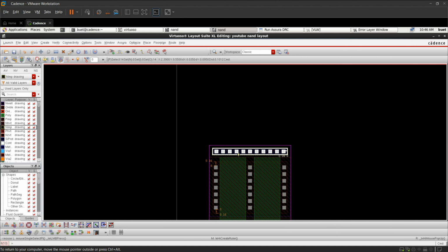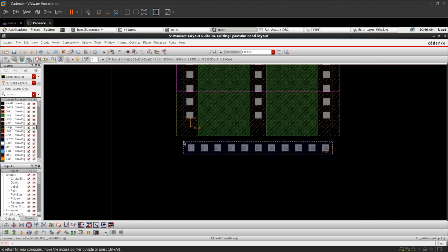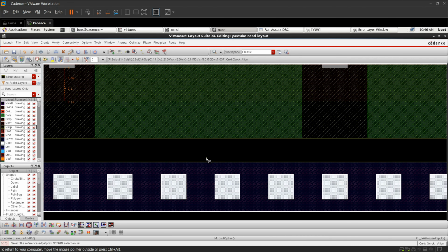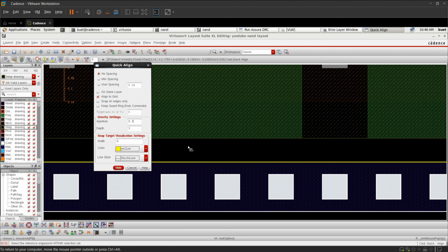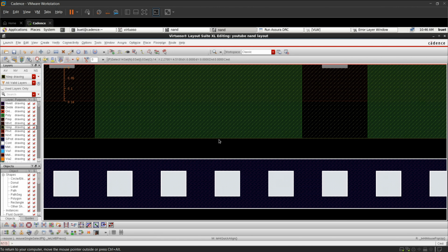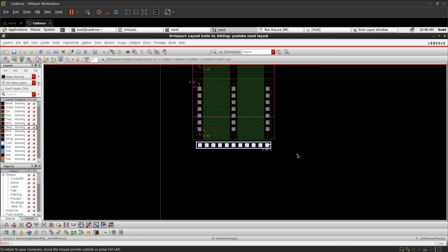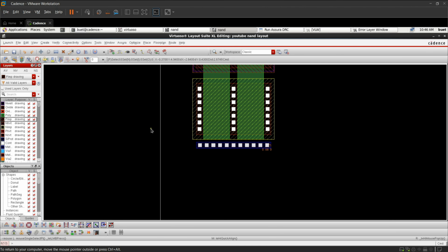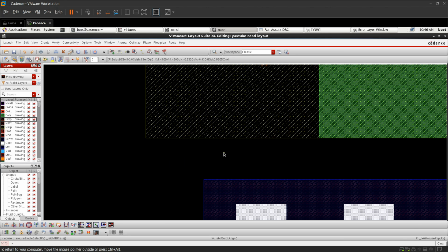As we have seen in here, the spacing between our poly to oxide should be 0.1. Okay, just keep it at 0.1 distance from poly, align, options, make it user spacing 0.1, hide. It is done.